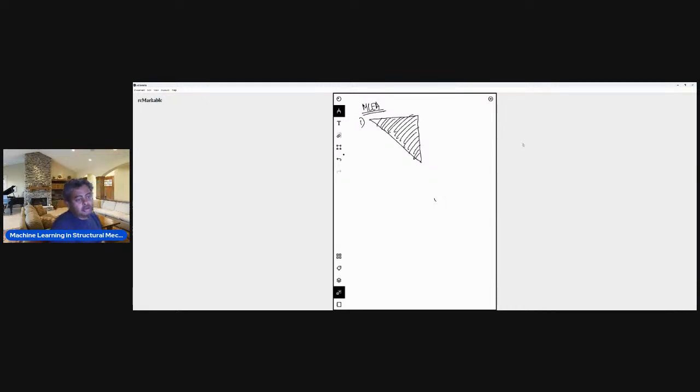So let's say we are talking about 24 DOFs, and for 24 DOFs, you will have 24 rows and 24 columns. But if you preserve the symmetry about the diagonal, then we are talking about 300 entries, because you can look at them as n times n plus 1 over 2, with n going to 24. 24 times 25 over 2, 12 times 25, is 300. So you have 300 entries which you need to take care of.